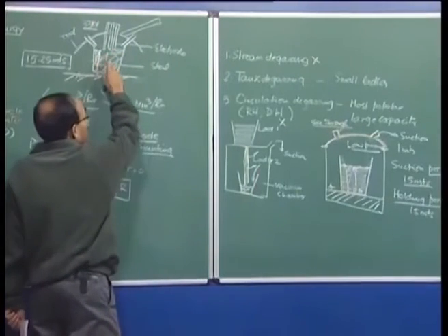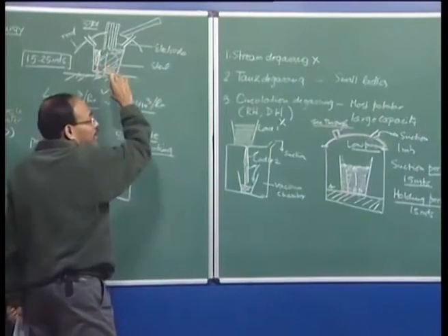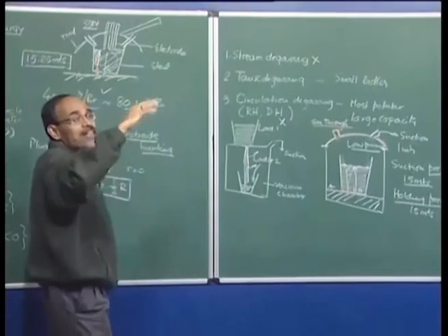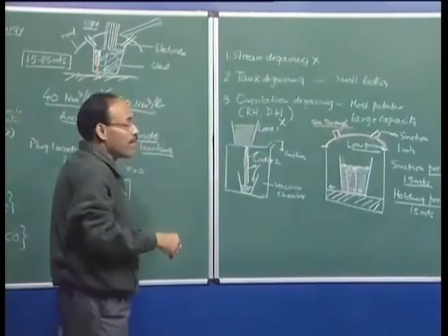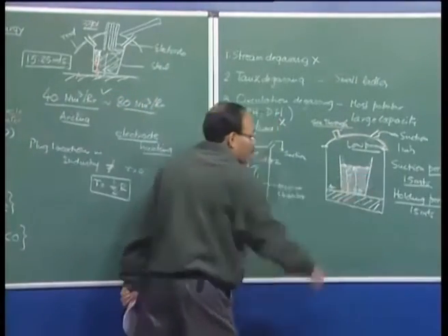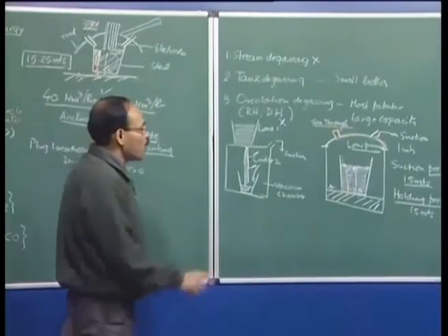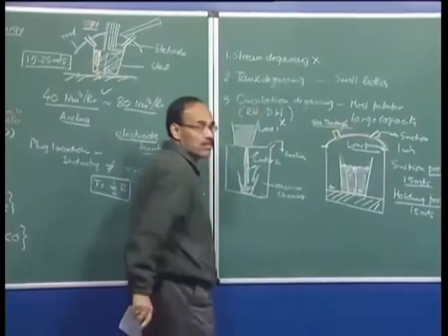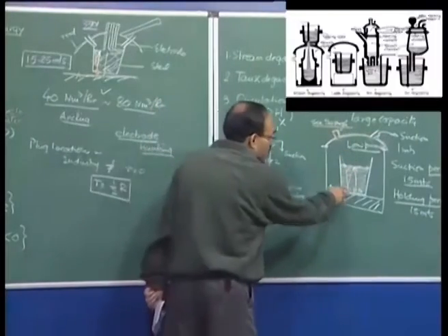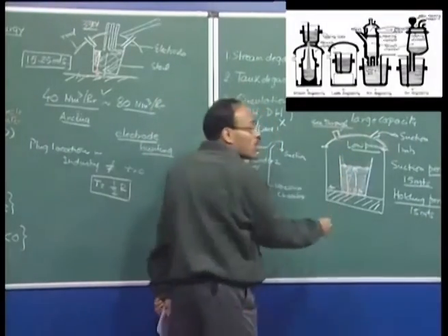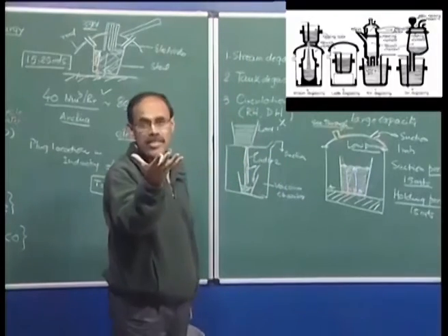So, therefore, the material which comes from the LF is at a higher temperature than is required by the continuous casting bay in order to compensate for the temperature drop in the vacuum process itself. We must understand here that because the pressure is extremely low, the bubbles are subjected to just the ferrostatic head. So, the bubbles really grow enormously in the system.